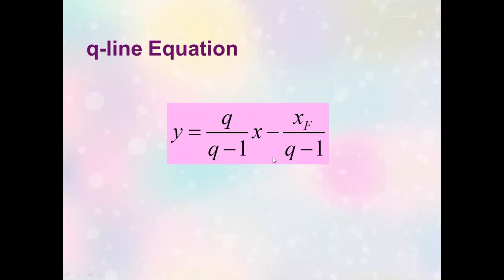The enriching section operating line simply follows the intersection of your feed line and the curve, so the three meet at one point. Since we don't have the equation of the equilibrium curve, what we use is just the equation of the enriching section operating line and that of the feed line. That would give us the x prime and the y prime for our pinch point. The equation used for the enriching section operating line is just so you are able to find the x prime and the y prime.